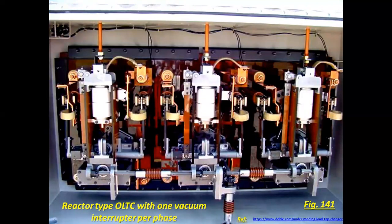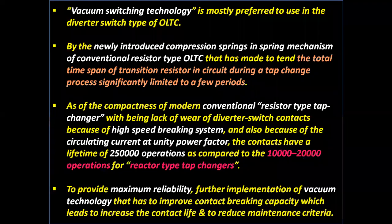Reactor type OLTC with one vacuum interrupter per phase. But in case of resistor type OLTC, two vacuum interrupters are required per phase. Vacuum switching technology is mostly preferred to use in the diverter switch type OLTC.